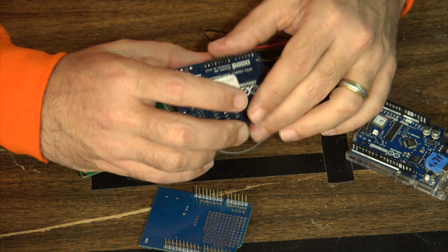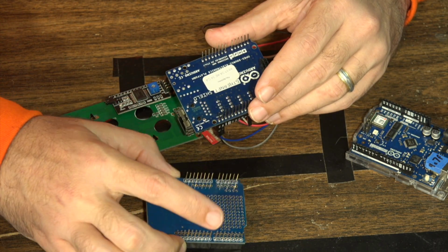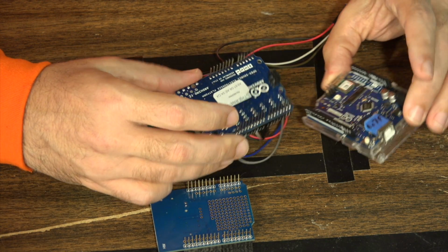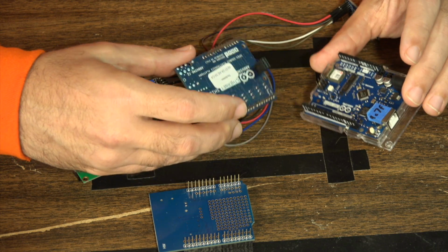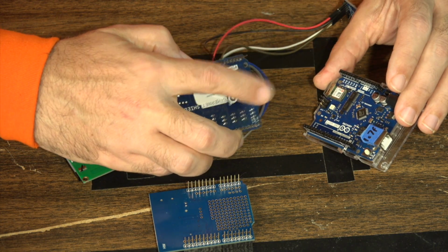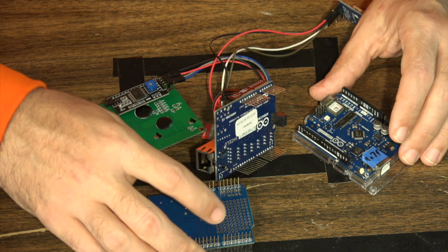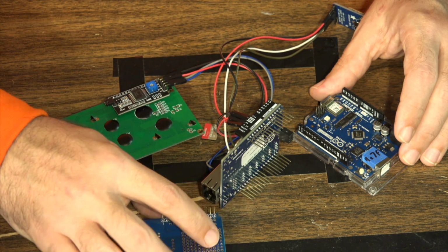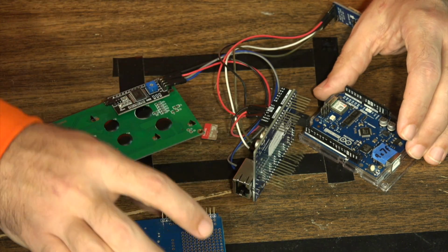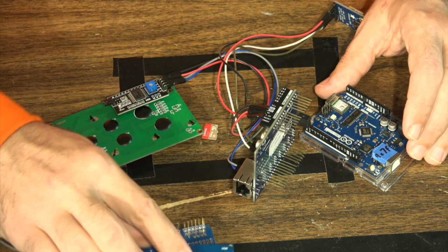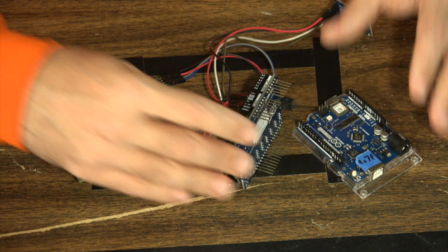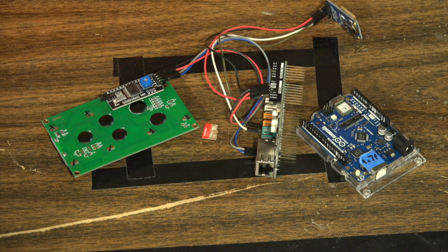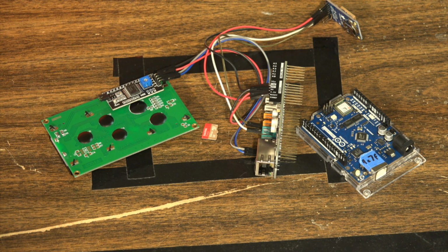Many times the shields without them will work fine, but for the Arduino Uno, at least as far as the SD card functionality is concerned, they need those ICSP headers. So if you're going to try to do this project with a different data logging shield, if nothing else, just make sure to get the ICSP headers, because this will not work. They all look the same, but they don't have the right headers. So that's some of the stuff to be thinking about with the physical build. With that, let's go over and actually take a look at the code itself.